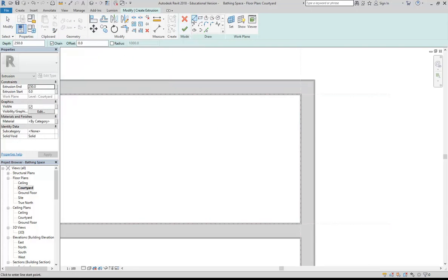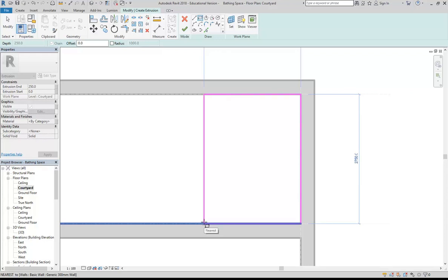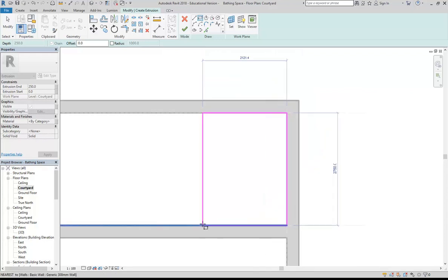So there you can see we've got the drawing tools, which are very similar to what you've used already to make things like floors. Right, so you've got all these tools to draw lines and other shapes. I'm going to go to Rectangle, and then just click on the corner there in the top right, and then go down and to the left, and line it up with the wall at the bottom. I'm not that worried about the width, I'll adjust that. So I'm just going to click there when I touch that wall, and give it a nominal width.